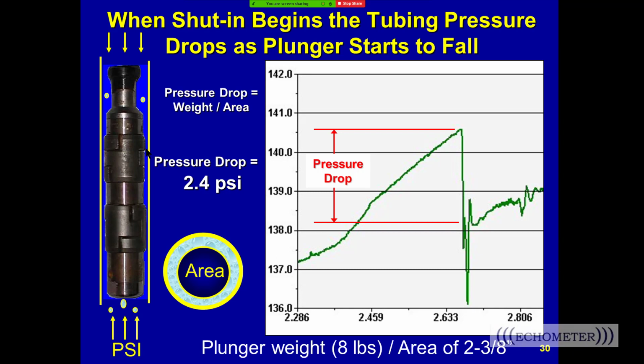And so you can still record tubing and casing pressure. We've got some data on some gas-assisted plunger lift wells, but we can't see the plunger because there's so much liquid, such a high liquid rate. Usually above about 100 barrels of liquid a day, you start to have the tubing fairly full of liquid, running some kind of continuous run plunger, and it becomes difficult to see the plunger because now the tubing is almost full of liquid. So it's typically a lower rate liquid well.